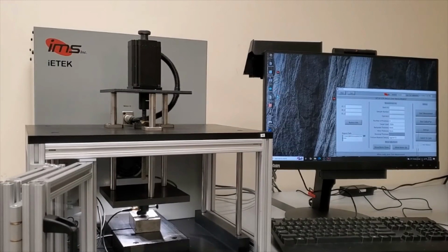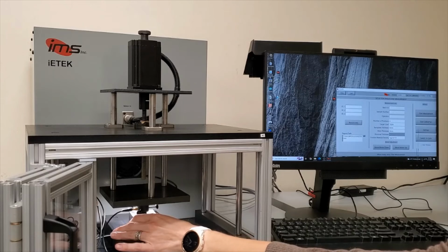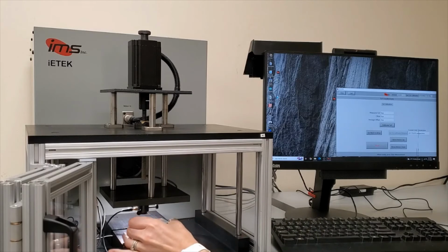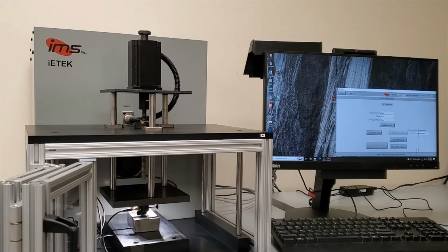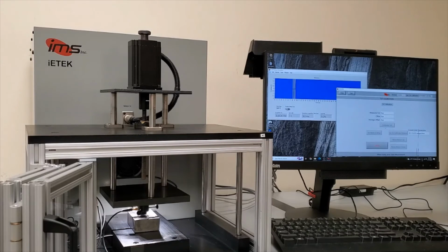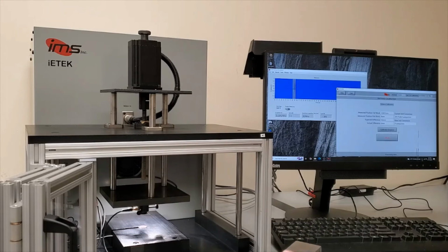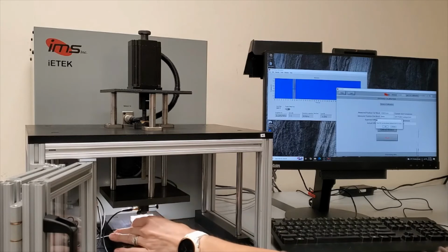Now, the other thing to look at is what you're actually doing when you're doing this GUI manipulation. This shows Loretta pulling out the 1-inch diameter gauge block. You insert that between the two transducers. You then press the gauge block calibration, the TOF calibration symbol. The platform moves down, measures the time of flight, compares it with a known time of flight, and generates an offset number.